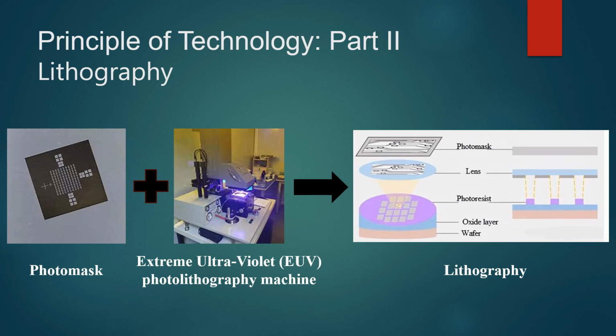The entire top surface then undergoes either wet etching or dry etching, or maybe we should call it a chemical reaction. The part where the photoresist remains will protect the substrate, finally making the desired three-dimensional pattern we want.